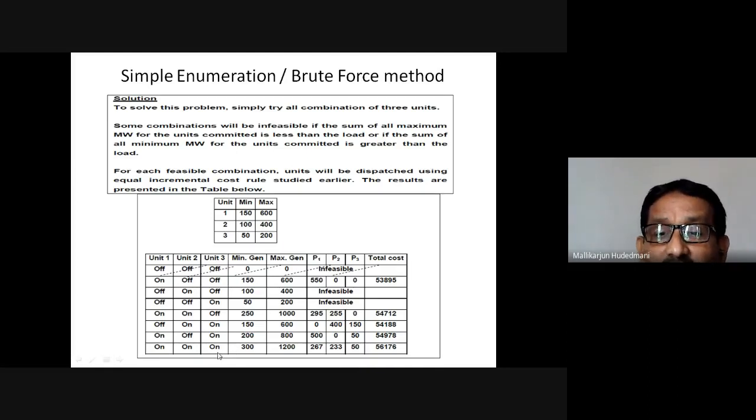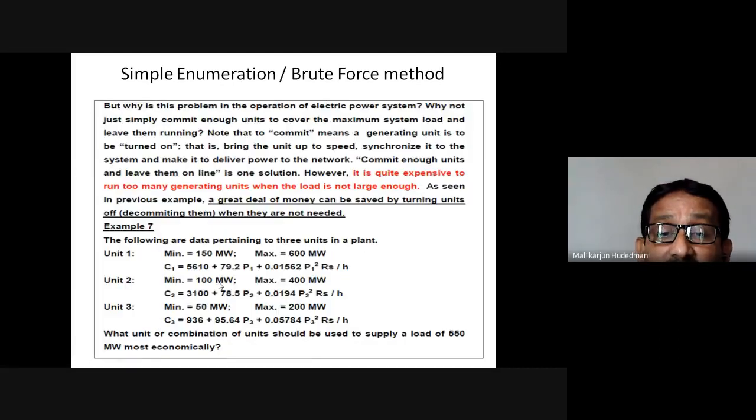Again the question comes. I have to go back to the previous slide where I have the fuel cost function of P1 from machine 1, P2 from machine 2, P3 from machine 3. I have to solve it again. My friends, you all clearly know that when we have two machines, it's very easy to obtain the economic set point using dC1 by dP1, dC2 by dP2 and equating them, with the total production value P1 plus P2 equal to PD. When more than two machines arise, the best analytical method is to obtain the lambda itself.